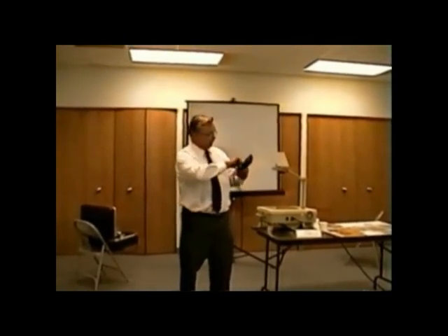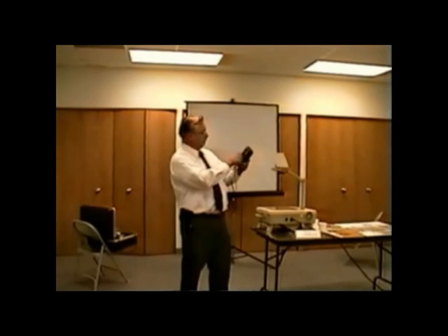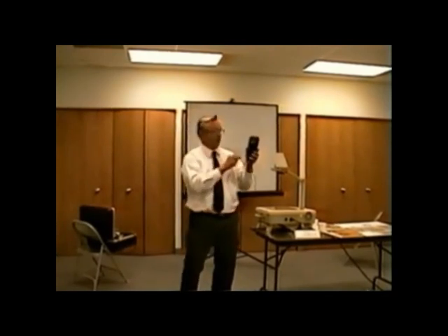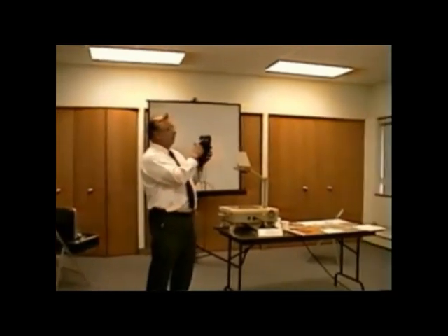But I says, so now he goes over here and he says, I'm going to put this on a scale. You really can't see the scale with the camera. But he says, I got 13 microamps. He says, I'm using it right now, right in front of the furnace. I got 13 microamps. And I said, really? I says, what scale are you on? He says, I'm on the microamp scale. I says, but which one, AC or DC? And that's the point. He had it on the AC.